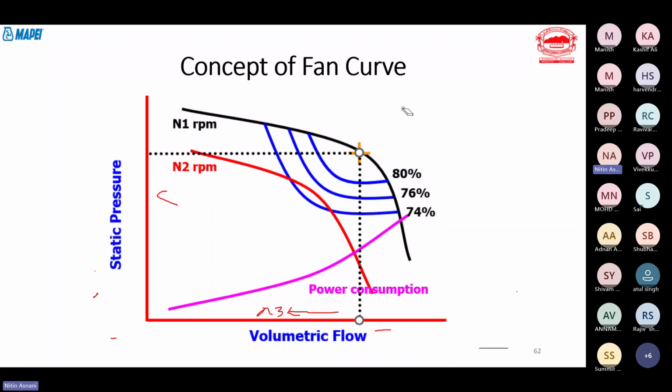So generally, what will happen in that case? Suppose you reduce the pressure drop by 50 mm WG. How much saving will you get? In that case, you have to reduce the fan RPM to maintain the same nozzle velocity. If you reduce the fan RPM, automatically you will get the benefit in saving. Suppose you reduce 50 mm WG, then 50 divided by fan head into coal mill fan power will give you the answer.